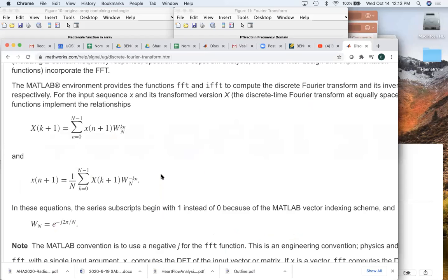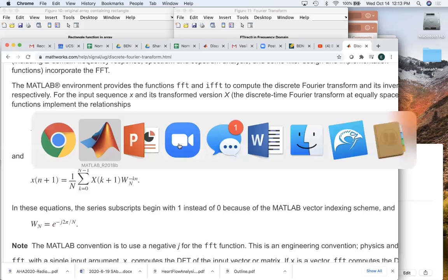So it's here. We're going to replace this, instead of 0, with 1. As we sum over this, it'll be e to the minus j 2 pi 1 times little n over big N. What's going to happen is that this term, as we do this sum, is going to go through one full cycle of a cosine.